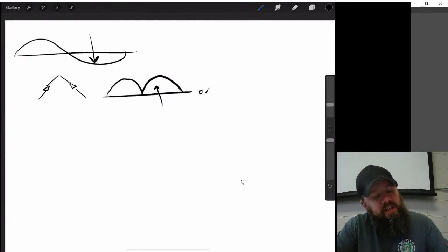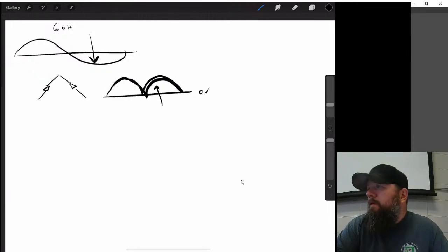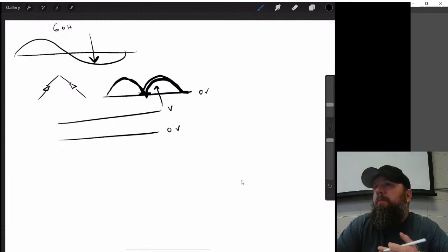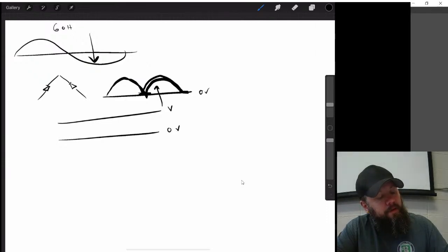If this is 60 hertz and you flip it up here, what have you got? You've got something that's double the frequency. So 120 times a second, you're going down to about 0 volts, right? All right. So we want something that looks kind of like this. So we've got 0 volts here and some voltage up here. We want it as smooth as we can get it, right? So we'll put it through a capacitor.